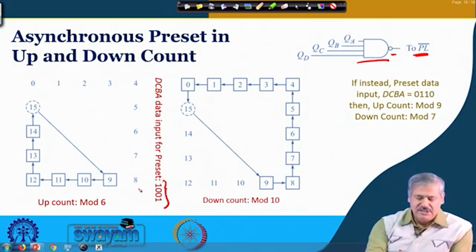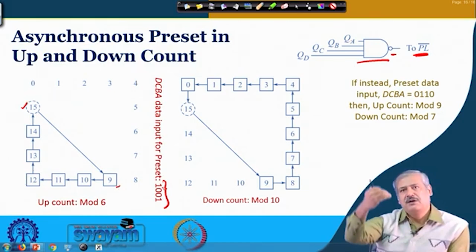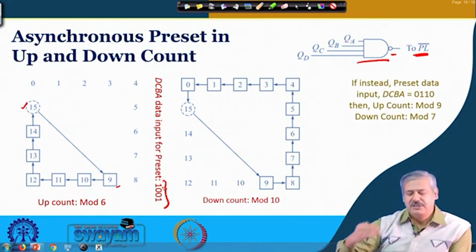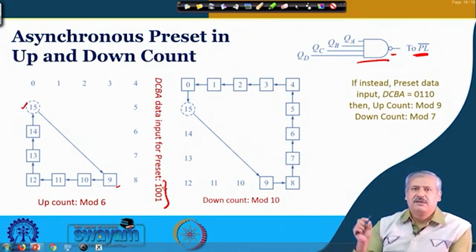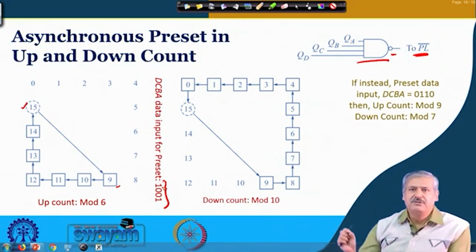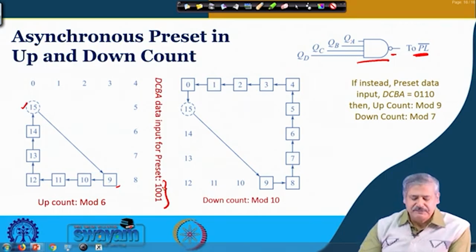Whenever this reaches 15, immediately within that clock cycle, the way we had discussed for the 7490, 9 gets loaded, because it is now variable preset. So, now it is 1001 like before, but we have put external values 1, 0, 0, 1 separately. Earlier, for the 7490, 1001 was internally getting preset.